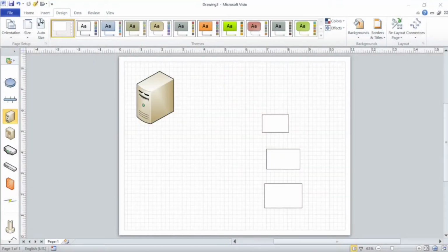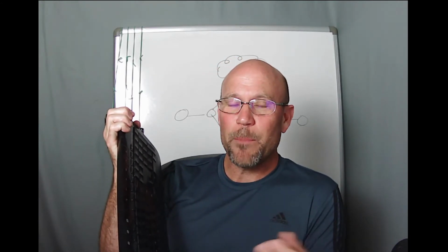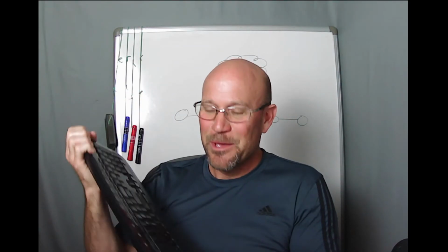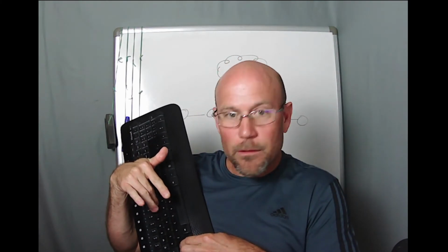Okay. So let's get back over there. Let's look at that. Control G. Now, to make them not one object, let me check myself on this. Yeah, okay, I got this right. So Control G groups them. I wish it was Control U would ungroup them, but it's actually Control Shift U. So Control Shift and then the U key. You see that? Some people will use two hands to do that. Control Shift and then the U key.